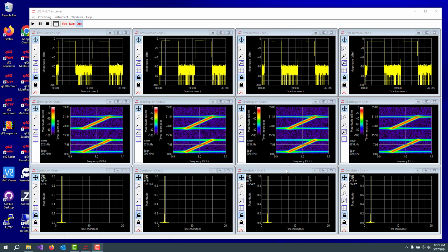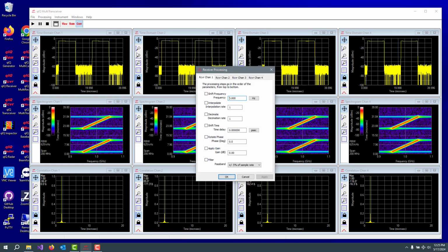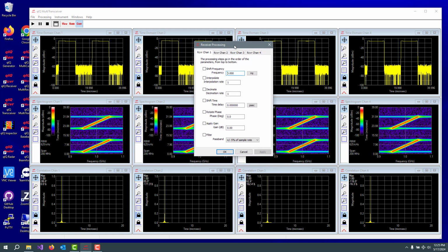Our previous measurement convinced us that all 4 of the receiver channels' LO stayed locked with respect to each other. What this is showing in addition to that is the 4 transmit DAC LOs are staying locked with respect to each other. As a final step in the process here, let's add some receiver waveform processing to get rid of that phase difference between the channels.